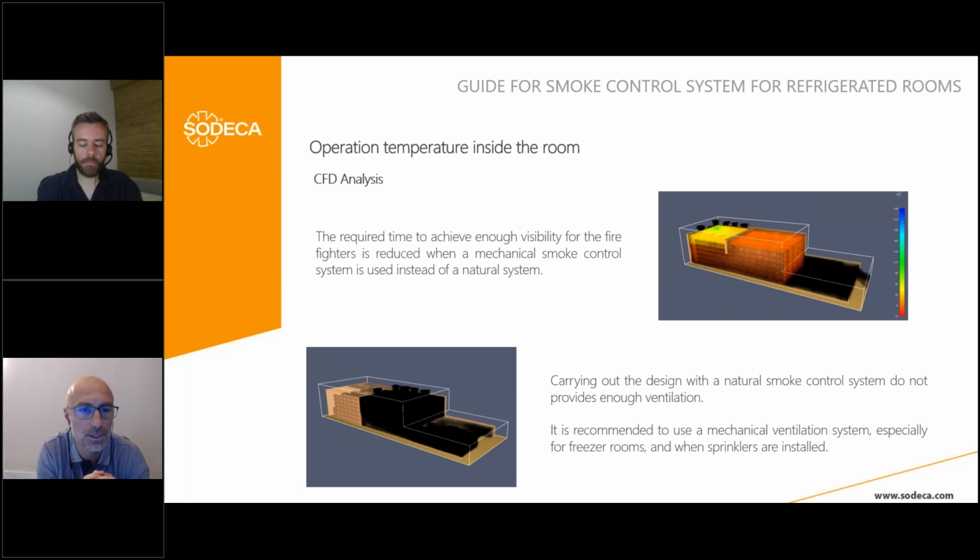And the second conclusion was that carrying out the design with a natural smoke control system does not provide enough ventilation. So it is recommended to use a mechanical ventilation system, especially for refrigerated rooms when there are sprinklers in the room.